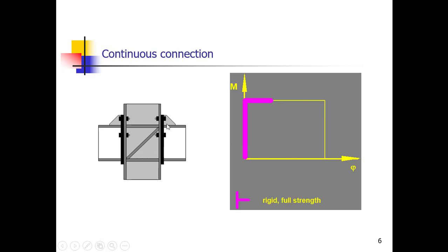Here, because of the ductility present in the connecting element, say a header plate or extended plate used to connect the beam to the column, some bolts and bracing plates are included to increase the rigidity of the connection. Therefore, from the graph, it is the ideal behavior of a fixed connection, that is, complete moment is transferred from beam to the column. So such connections are said to be rigid connections.